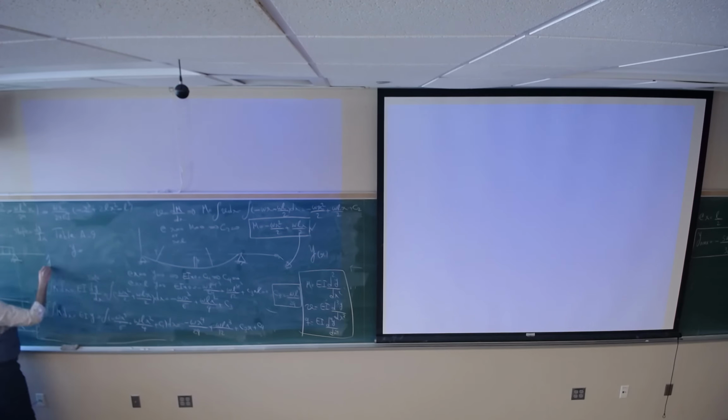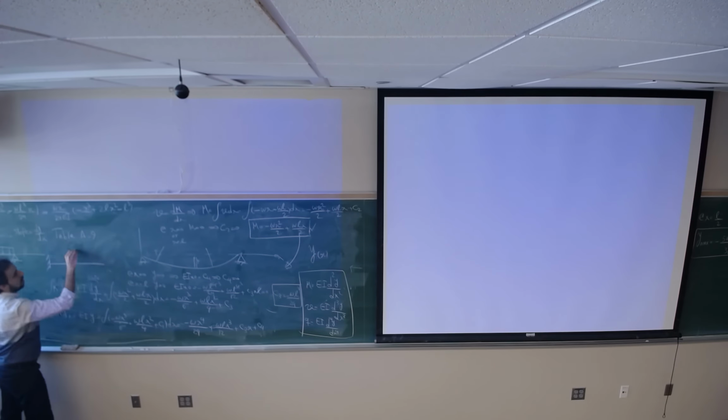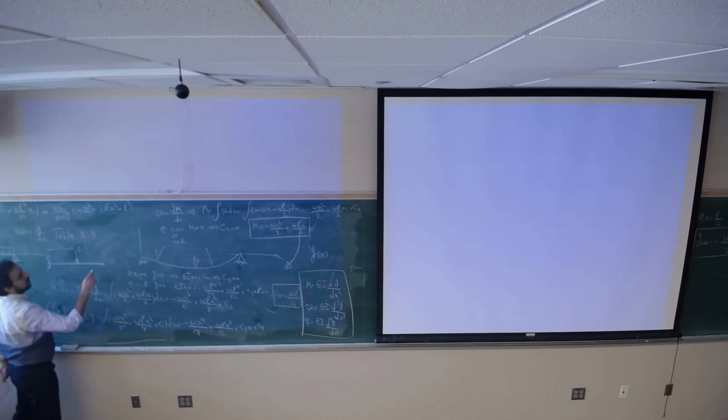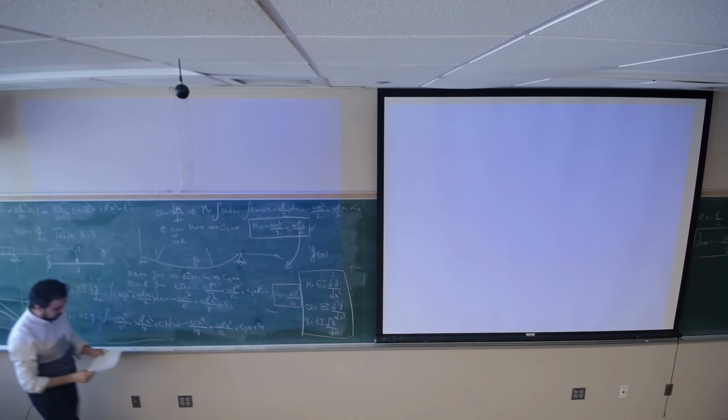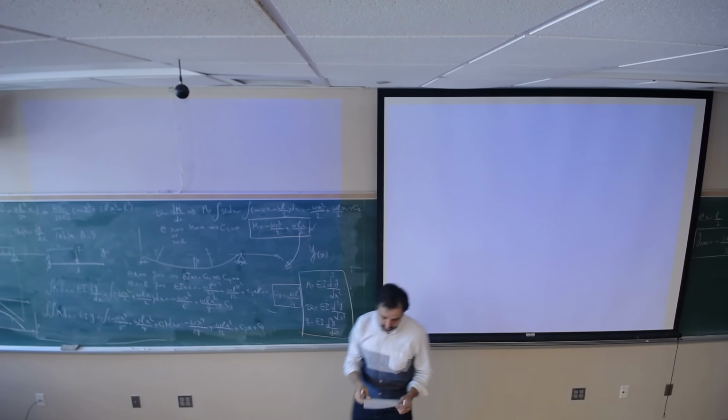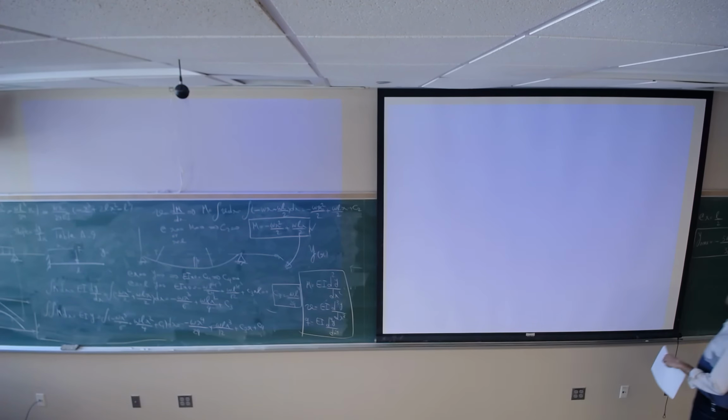If you look at that, if one force at the distance of A and the length of L has been applied to this cantilever beam, what would be the Y? You can find the Y from Table A9. So there are some standard configurations there that you can look at for those functions if you don't want to derive them.